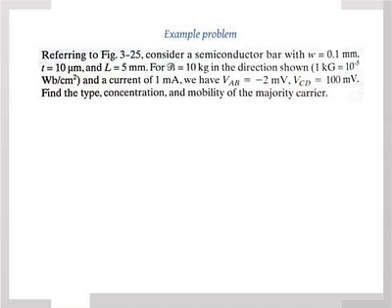So what I said just now is not the actual logic. Okay, let's go through this again. Why are the carriers electrons? Let's think about this. The Hall voltage that appears is negative. Not the applied field, applied voltage. The Hall voltage that appears in the material, the built-in voltage, V_AB, is negative. Okay?